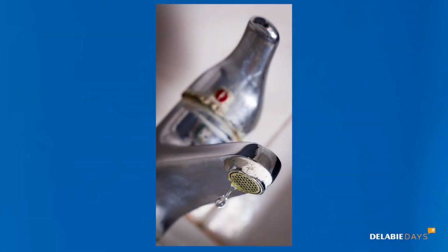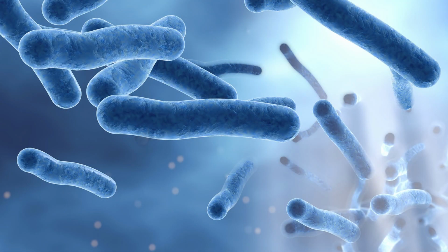I cannot go into all the detail here, but there are other factors such as scale or a large number of impurities in the hot water production and storage equipment and pipework, as well as non-return valves that are no longer watertight, and even cold water temperature around 30 degrees Celsius due to poor pipework insulation. All of these can contribute to microbial proliferation. As you can see, the problem is very complex.